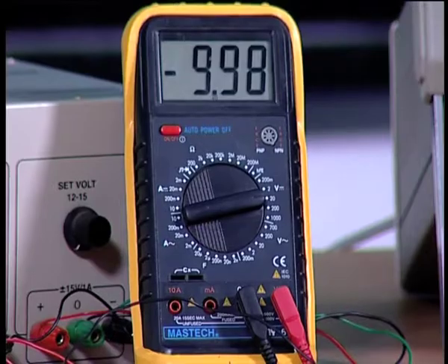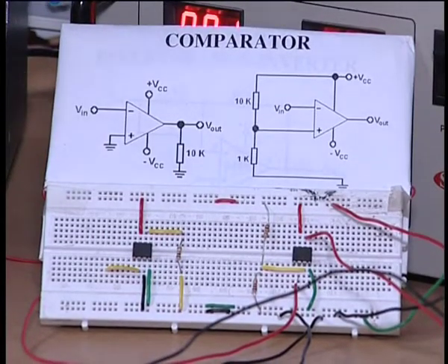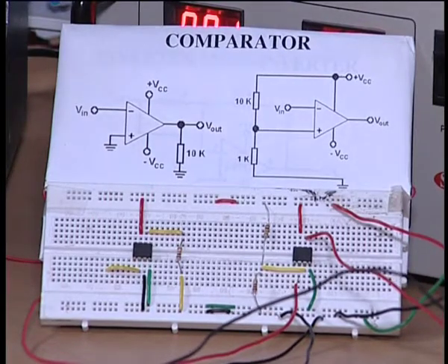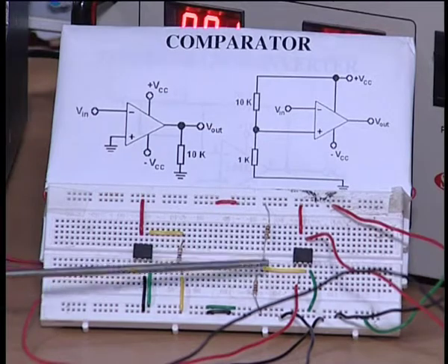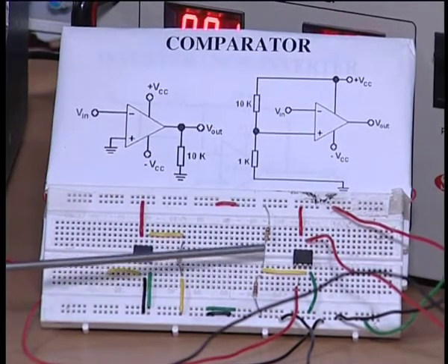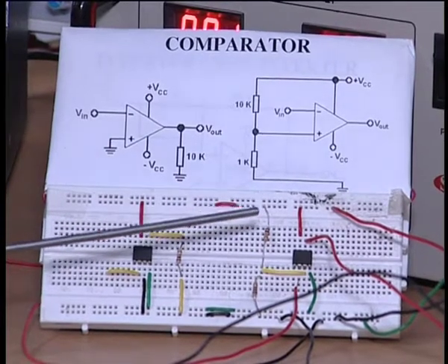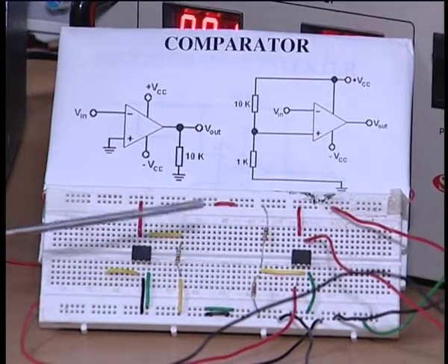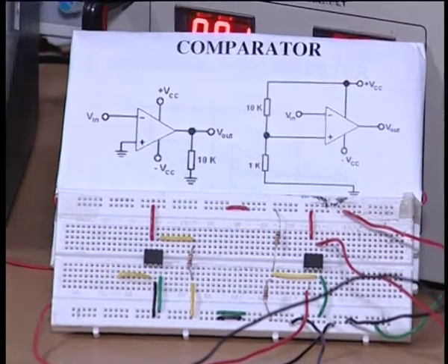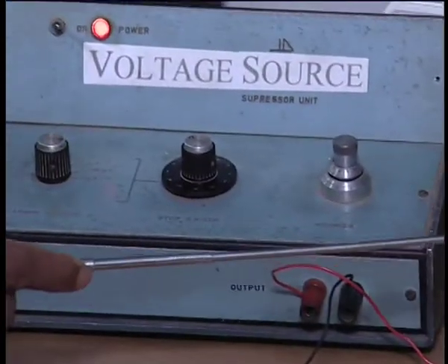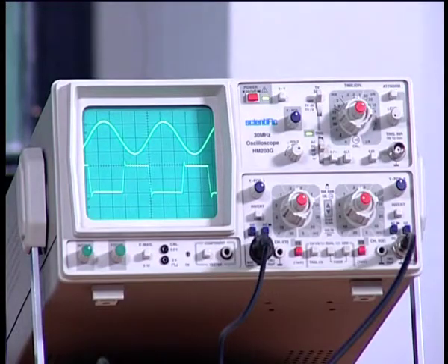So this shows that the comparator is capable of detecting voltages within the range of 1.2 volts plus or minus 120 microvolt on either side, that I was mentioning to you, and therefore it can be used to compare two different voltages. Now what I am going to quickly do is modify the circuit and go to the second circuit. Now I want you to look at the second circuit.